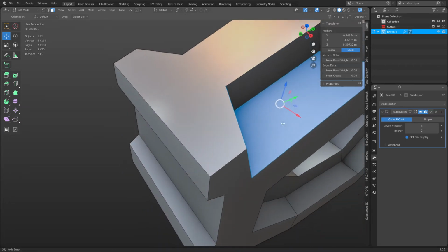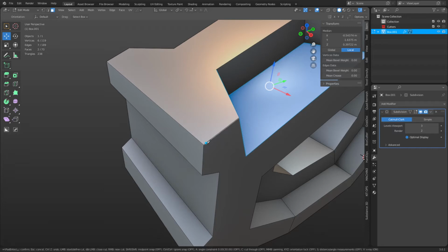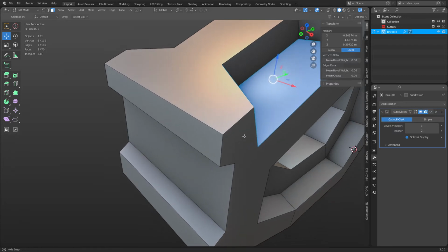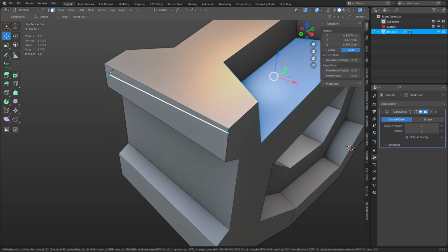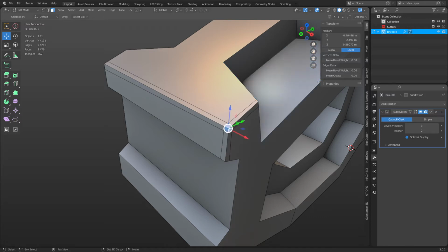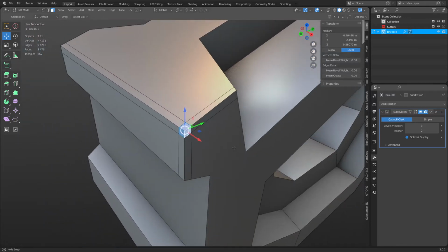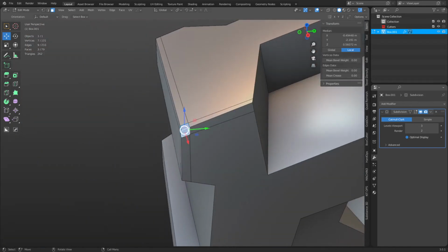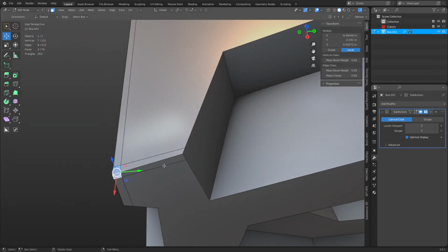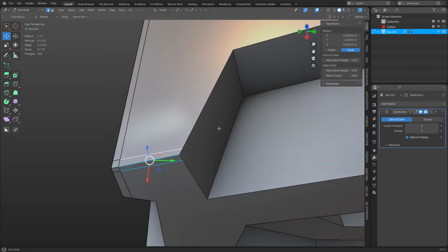And so if you followed along with my other videos, you'll know there's two different types of holding corners I talk about. And one of those being this corner here. Okay. I'm going to start cutting it out so you can see what's going on. This is what you'll more than likely be looking at for a corner like this. Okay. That's one type of corner you can create where it's 3 quads in the corner. You need 3 edges to hold a sharp edge, right?